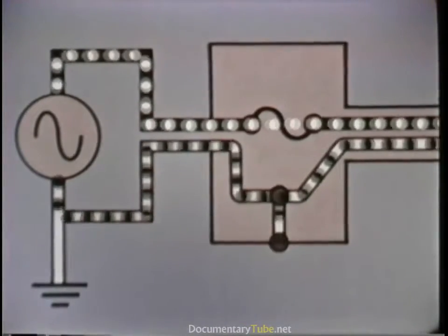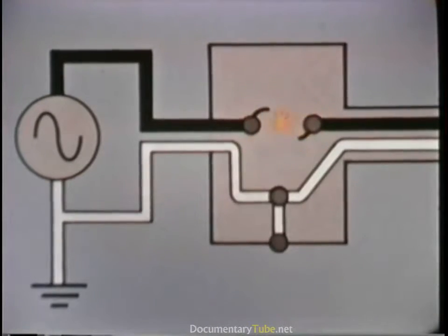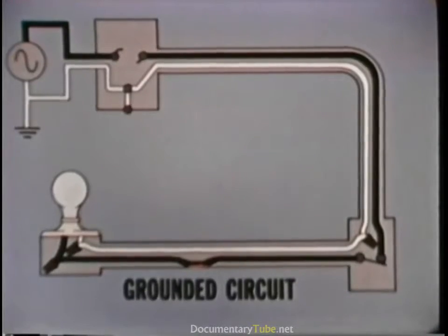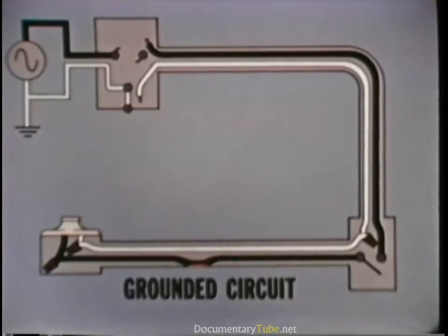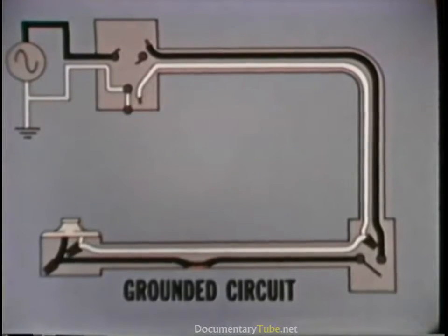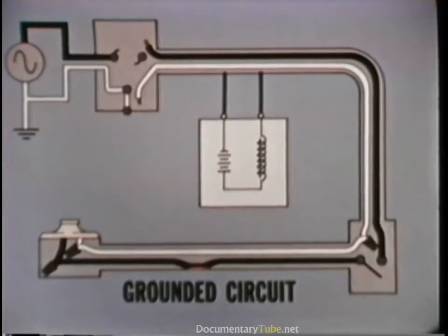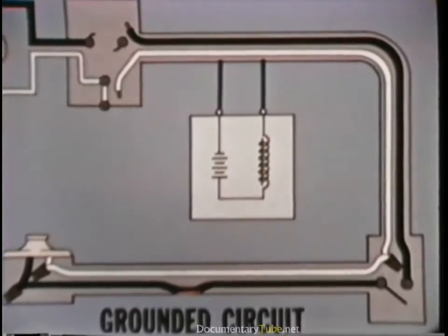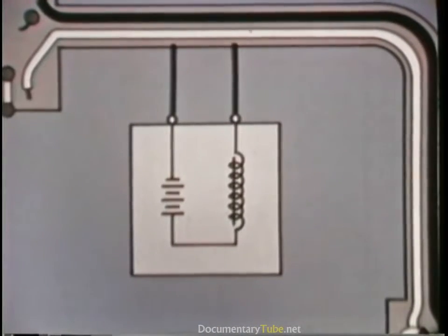This time, let's examine another case where we come on the trouble site to find a blown fuse. Once again, to deal with the circuit safely, remove the wires from the power source. Remove the other elements in the circuit by opening the switch and removing the bulb. This time, instead of using a multimeter, let's use a buzzer-type continuity tester. This tester is simply a small door buzzer and a dry cell battery.